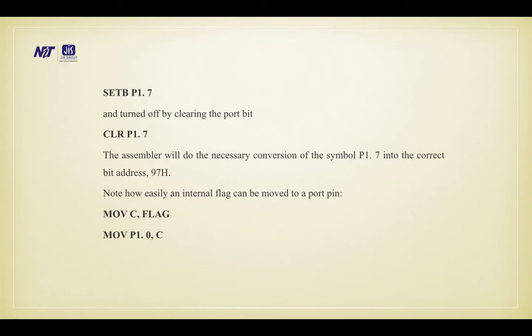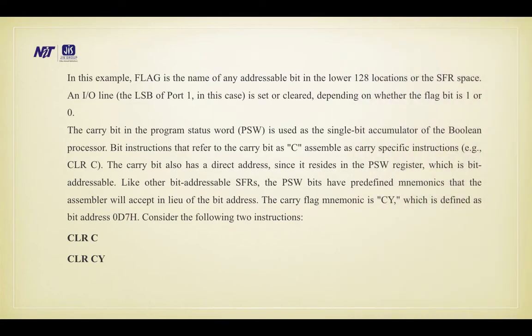Note how easily an internal flag can be moved to a port pin. MOV C, flag; MOV P1.0, C. In this example, flag is the name of an addressable bit in the lower 128 locations or the SFR space.